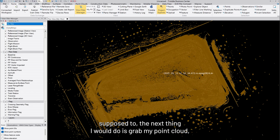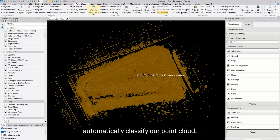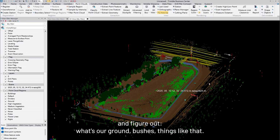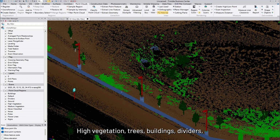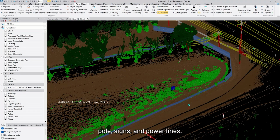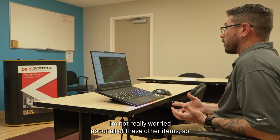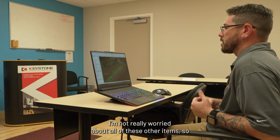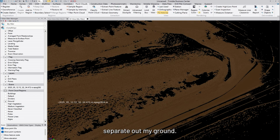After I've done my QA/QC to make sure it's landing where it's supposed to, the next thing I would do is grab my point cloud, come into my point clouds tab, and tell it to automatically classify our point cloud. The software runs through and figures out what's our ground, bushes, things like that, high vegetation, trees, buildings, dividers, pole signs, and power lines. For an elevation model, I'm not really worried about all of these other items, so I'm going to actually just separate out my ground.